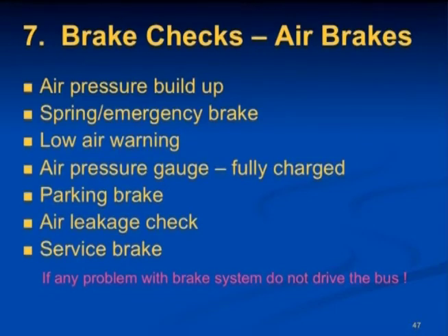If you have air brakes and you pump down as part of your post-trip inspection, check the brake system as you build up the pressure. Check the rate of air pressure buildup. When the engine is at operating RPMs, the pressure should build from 85 to 100 psi within 45 seconds in a dual air system. If the air pressure does not build up fast enough, your pressure may drop too low during driving and require an emergency stop. So don't drive the bus until you get that problem fixed.